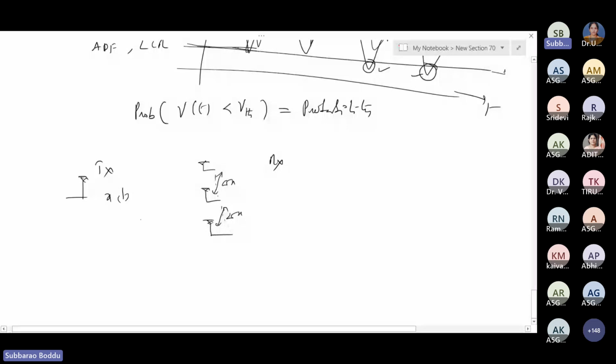I transmit a signal x of t. It means we receive another copy of the signal at antenna 2, another copy of the signal at another antenna. Here the distance of separation is very important, note down. If this distance of separation delta x is less than the coherence distance, the signals received at two antennas are correlated. Whereas if delta x is greater than the coherence distance d_c, then we say that they are uncorrelated.